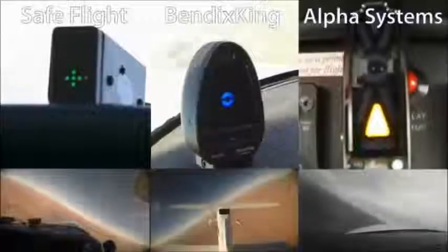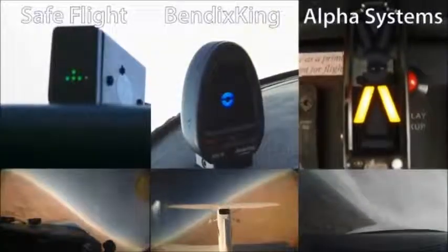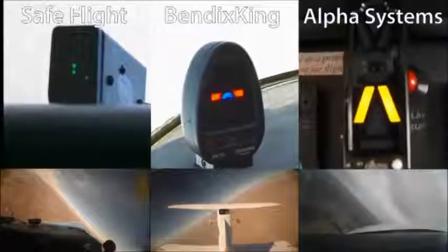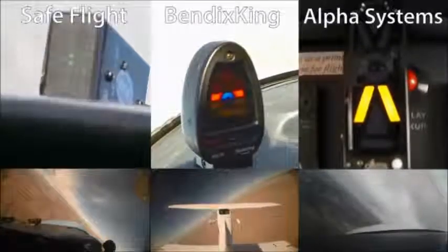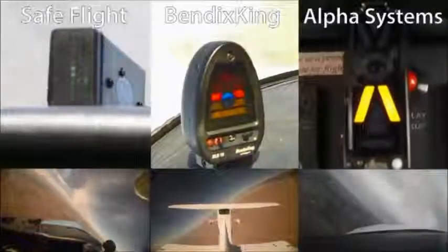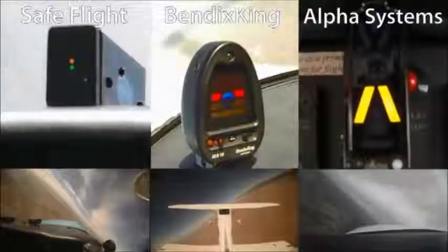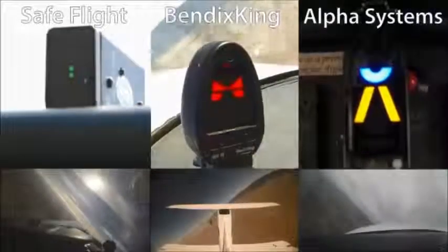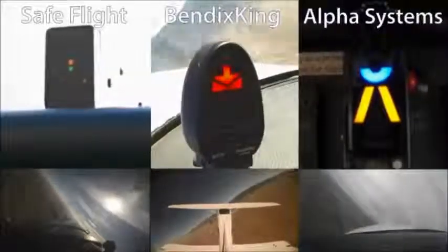Let's take a look at some steep turns. Performing this maneuver with these devices is a great demonstration of how the wing increases in load factor during a level turn. With the displays, you can visually watch the aerodynamic change as the bank angle increases. This is an indication of the increasing load factor on the wing, which requires an increased angle of attack to maintain altitude.